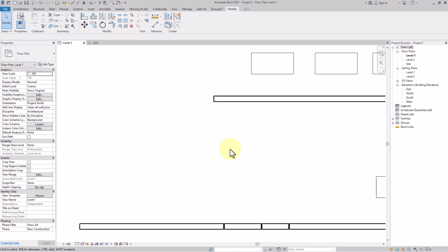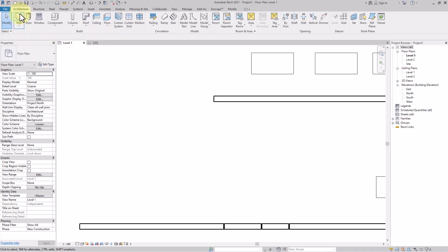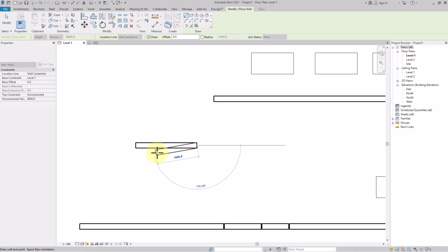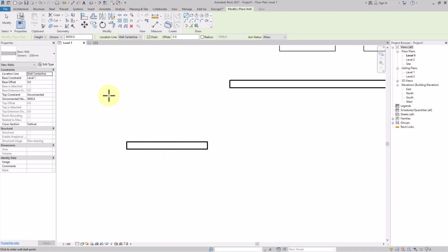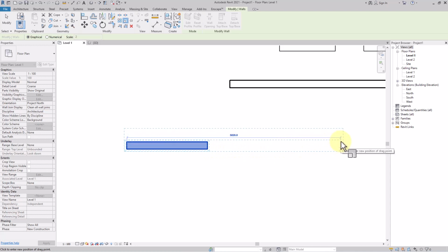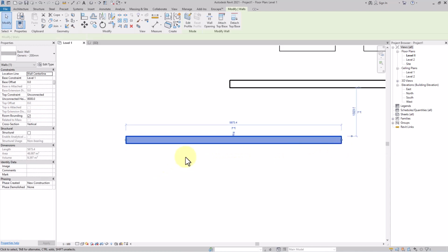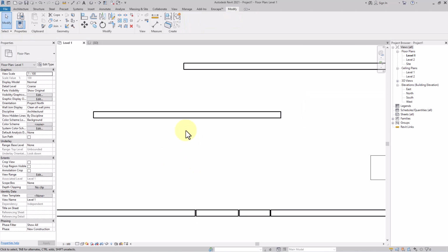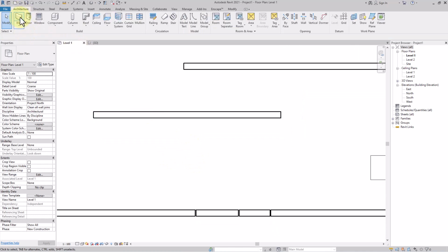Next we have scale, right? We use the scale command also. For example, if you have any wall and you want to scale it, then you can also do it. Go to the scale command and select the object and enter. Then the base point, from here you want until here. Now you can just make it scale how much you want, right? So it's very easy.